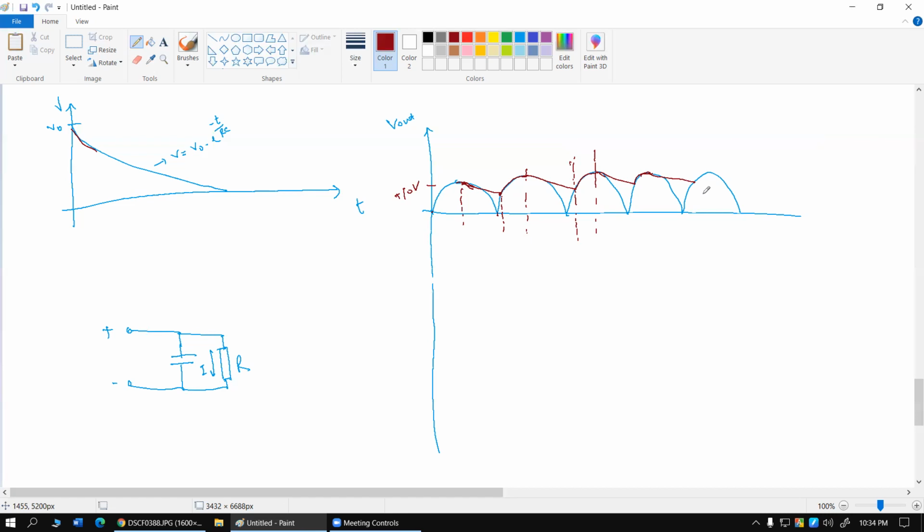So this is the primary thing: with the capacitor, it charges for a short time, then when the supply voltage drops, it discharges itself and tries to give our load a fixed, or a higher amount of, voltage, and when the supply voltage rises again, it charges again. That means continuously the capacitor will keep on charging and discharging, and in this process it will try to maintain a more or less uniform voltage, but this voltage is actually not so uniform because you can see over here for this graph that